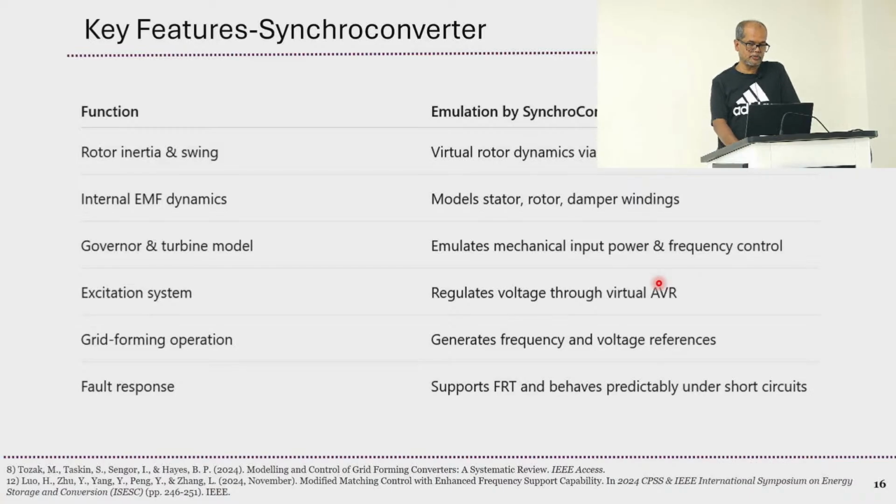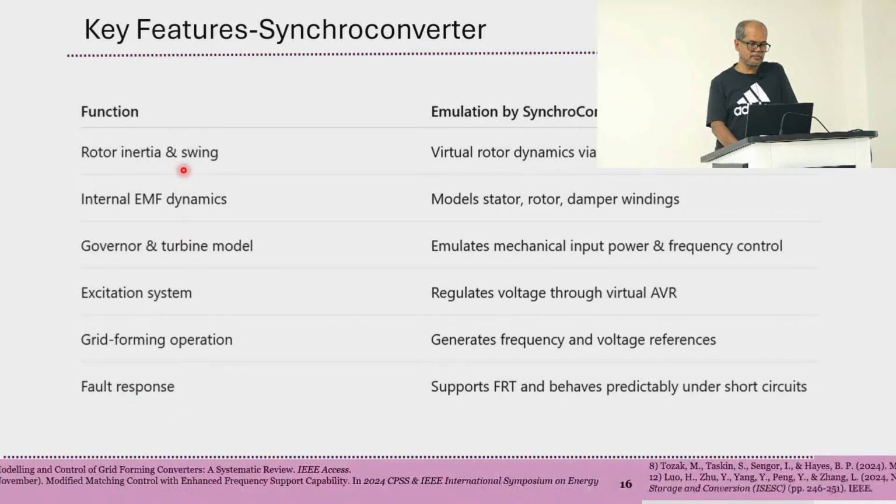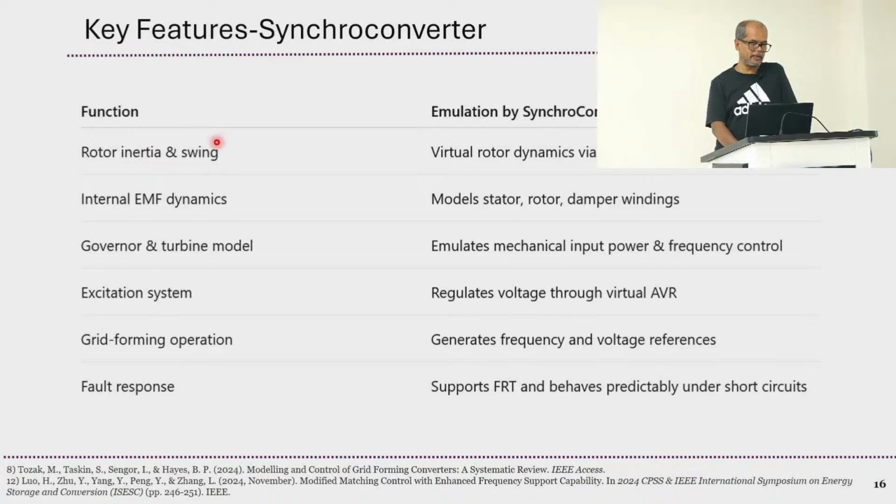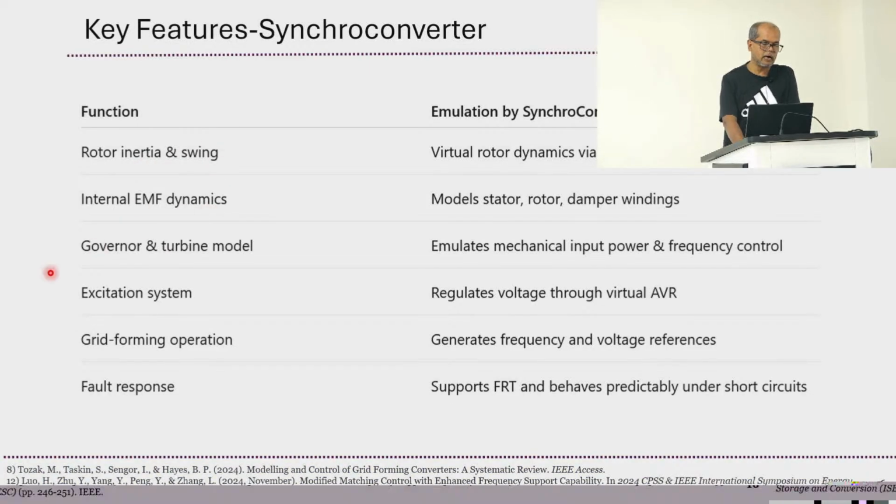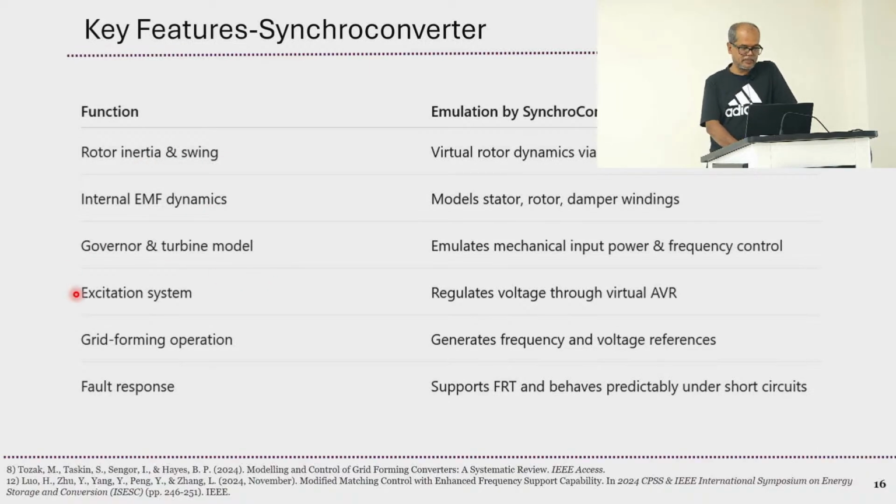Again, as I mentioned, it does consider everything that you would see in a synchronous generator: rotor inertia, swing, internal EMF dynamics, governor, turbine, excitation system.